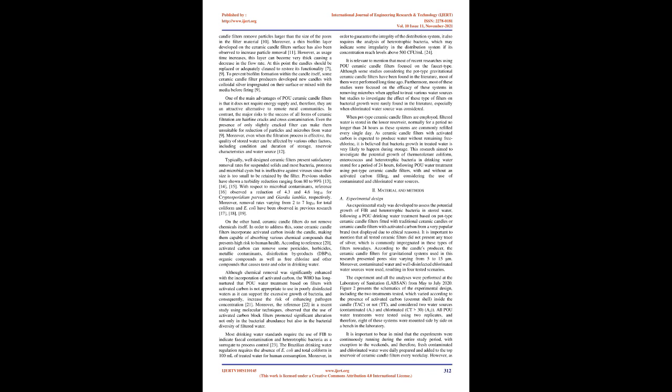This research aimed to investigate the potential growth of thermotolerant coliform, enterococcus and heterotrophic bacteria in drinking water stored for a period of 24 hours, following POU water treatment using pot-type ceramic candle filters, with and without an activated carbon filling, and considering the use of contaminated and chlorinated water sources.